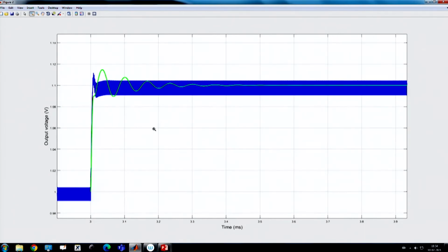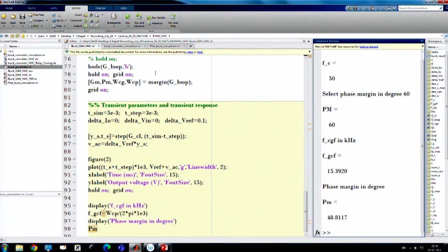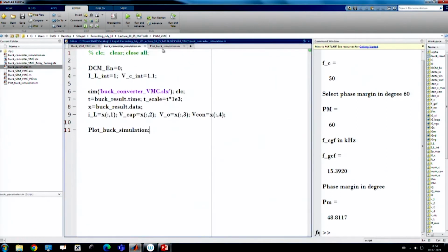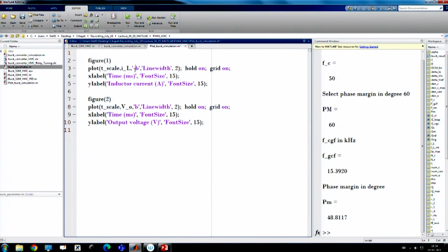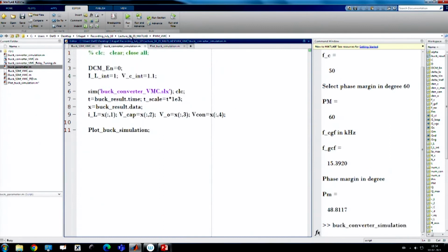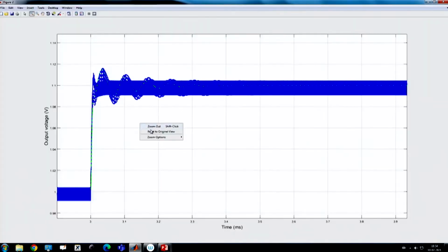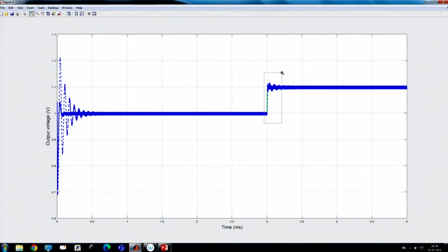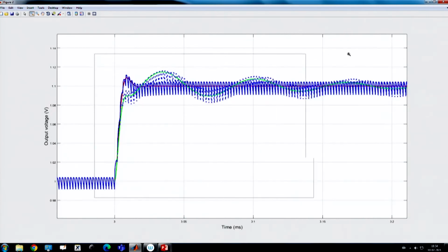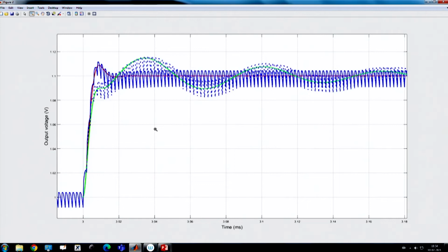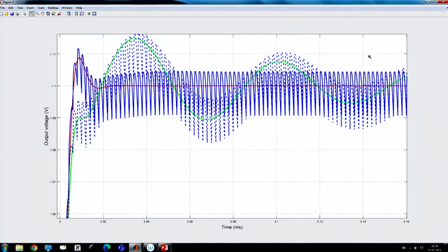Okay. So, here probably we need to trade off. Now if you go back to our converter response, if I draw the dotted line. In terms of design, this is not a bad design, but it is a more robust design, where it may have a little longer settling time, but that is fine, and at least it is insensitive to parameter variation.